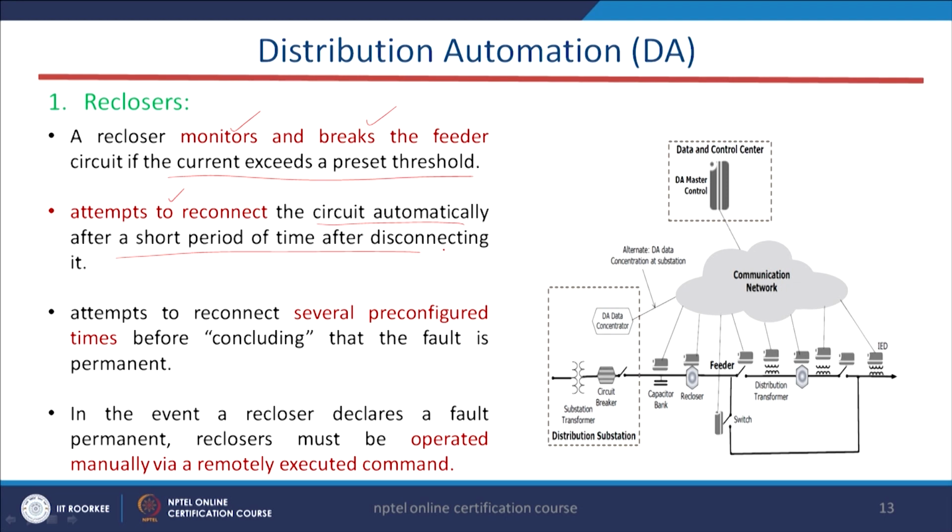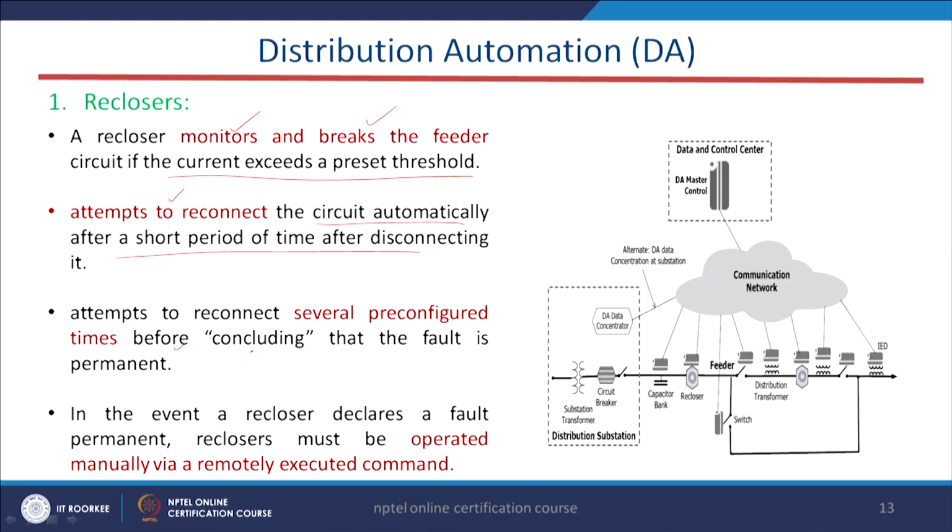It takes some time, and again it reconnects. It will do this several predefined times before concluding that the fault is permanent. Now, in the event that the recloser declares a fault permanent, then the recloser must be operated manually or by a remotely executed command.